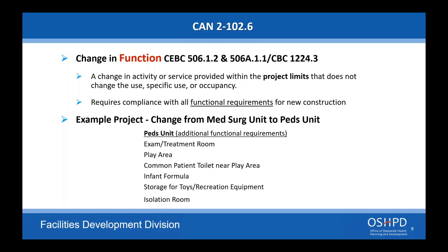Your anchorage and the attachment and the installation of that new generator do need to comply with current code. If you have issues for exhaust pipe locations that are non-compliant with the current code, but they are compliant with a previous version of the code, that is okay.